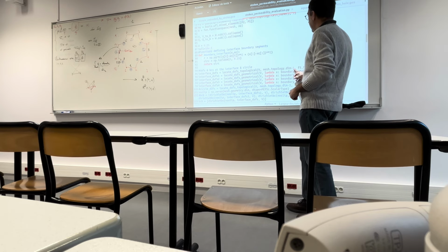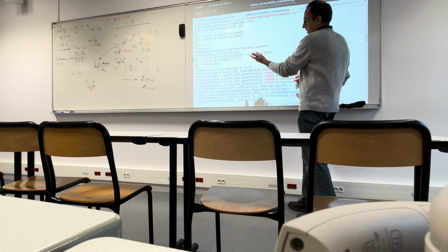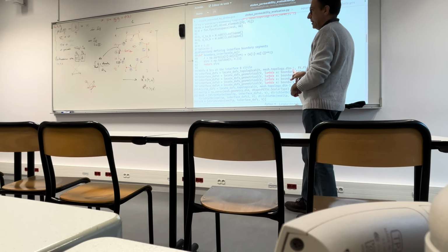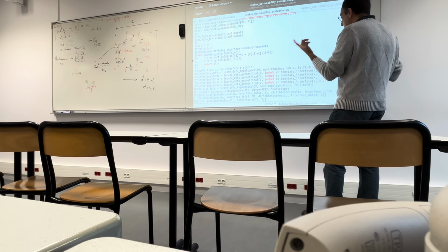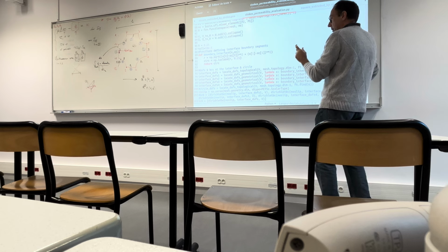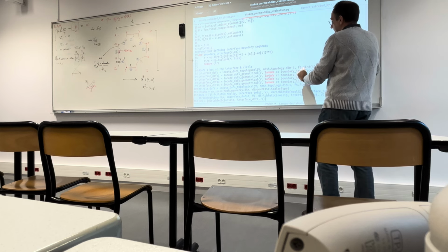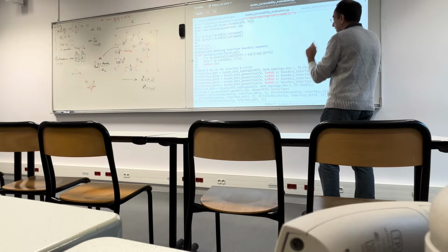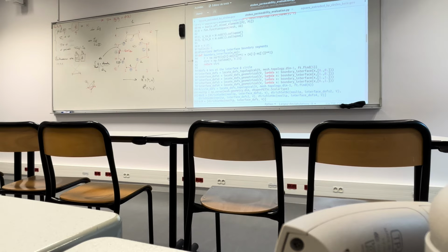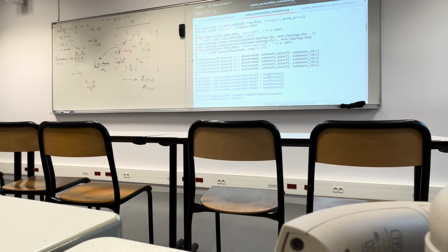Having a dimension which is the dimension of the mesh minus 1, so in our case 1, because we are on the boundary of the domain, and where I have to look for this degree of freedom. Here, Ft is the subdomain of the facets that we have defined before, if you remember. Here, Ft was the reading of the facet mesh XDMF.